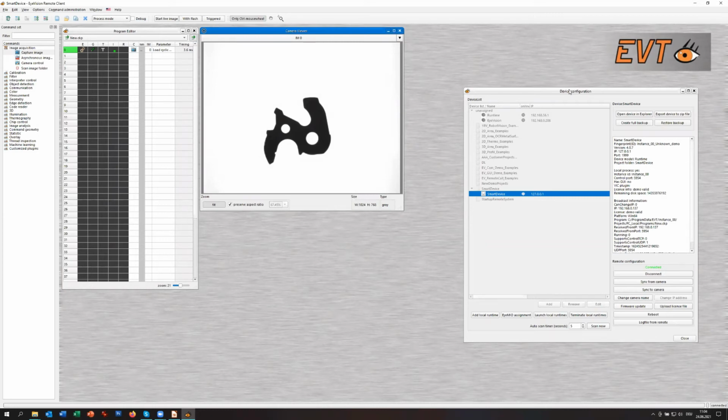Therefore, when using a smart camera or an embedded system, it depends on whether you need a finished system in a housing. If you don't, you can use one of these PCBs and integrate it in your machine. If you need a ready-made system, where you simply use the M12 connector and it runs, then a smart camera is the right solution. So it's difficult to say that a smart camera has this or that advantage.